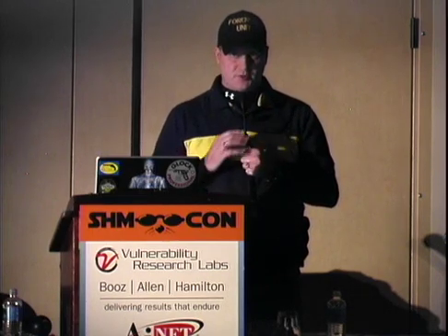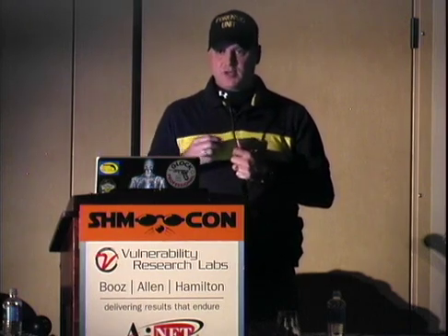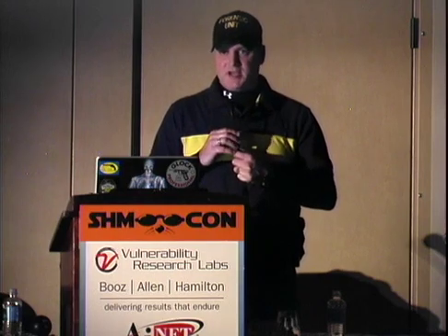Yes, sir. Next question? The second question from the streams was, how much of this technique applies to solid-state drives? Not very much of it. The only part that really applies is similar to this resistor problem, where we have a transient voltage suppressor. USB memory sticks and a lot of solid state drives have a similar resistor pack on their disk. The problem is that when they blow, they're a lot smaller and harder to find, so you really have to use a meter to test them. But in some cases, the exact same thing applies, where you can rip them off and then the drive will work correctly.